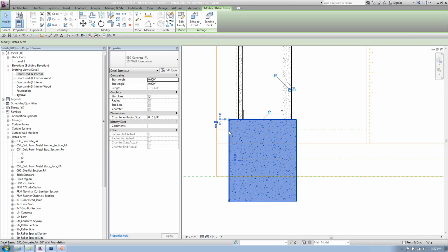Yes, you can. I don't recommend it. I was with a client, and they had spent like 4 hours trying to figure out why whenever they moved a wall, they had all these different walls they tried to move, they'd get like 50 error messages saying constraints not satisfied. And it would ask, what do you want to do? Delete 50 constraints. And they were freaking out, and we came to find out that what was actually happening is there was a whole lot of detail components aligned and locked to this. So as people started going through and moving a wall, it was trying to move the detail components, but that was also aligned to maybe a door in the project or something weird, and all of this craziness was happening.